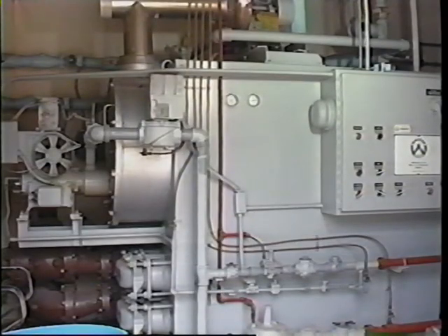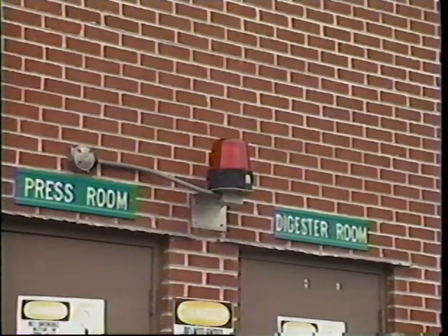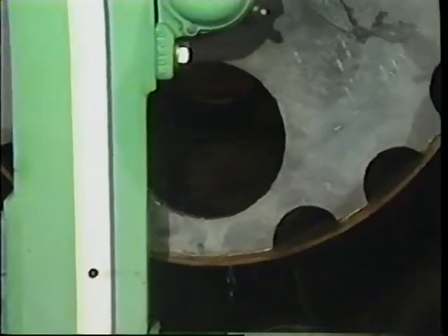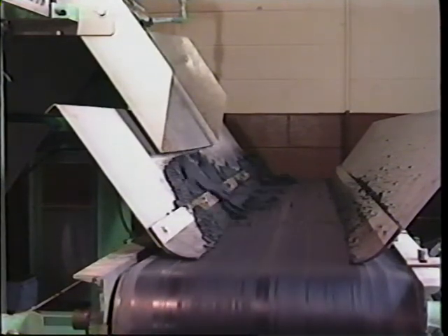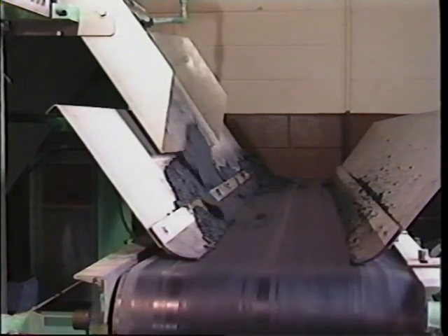The methane gas produced is usually used to heat the digester, but strict safety practices are imperative, for when mixed with air, gas from the digester is extremely explosive. Refer to Chapter 3 of the Field Study Manual for illustrations and detailed description of the complete biosolids digestion process. Treated biosolids from the digester are periodically removed for dewatering, processing, and disposal. Aerobic digestion may also be utilized to biologically treat the biosolids removed from the treatment process as well.